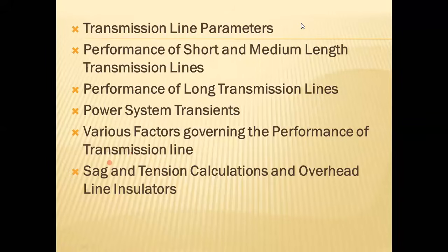And in insulators, we have glass insulators, pin insulators, shackle insulators, suspension disc, string insulators. When we come across string insulators, we'll be estimating potential distribution. Then the methods of equalizing potentials, capacitance grading, static shielding, all these aspects will be discussed in the last unit. With this, we finish this class, and from the next class onwards, we'll be starting with the first chapter, transmission line parameters.